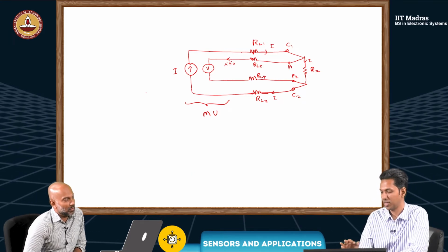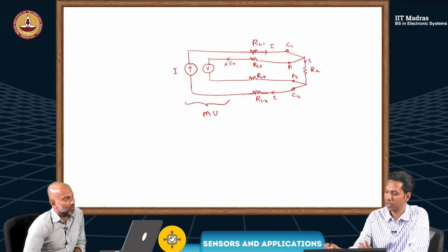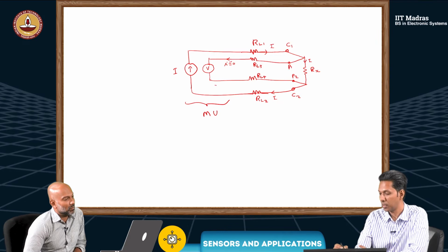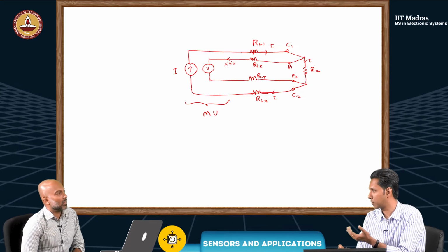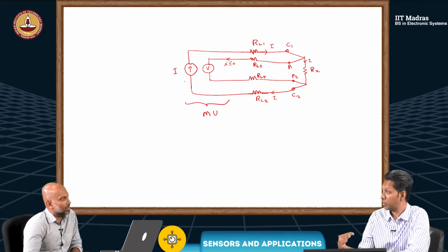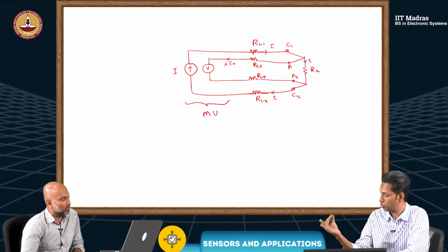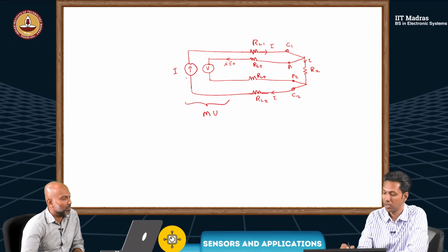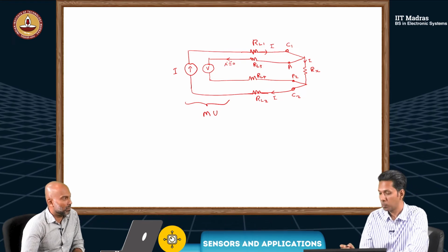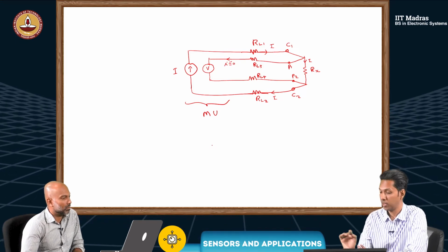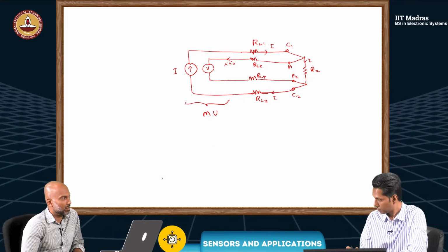This is a kind of surface level explanation, because to inject a current like this and then measure like this, you will need a voltmeter. Instead of a voltmeter, it may be an instrumentation amplifier, or an oscilloscope, which gives very high input impedance and gives an output voltage corresponding to this amplified version. The current source also needs some electronic circuit to introduce this current. But once you have this, you can make it independent of the lead wire resistance RL.